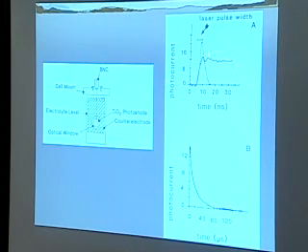I'll point out, when you're looking at the fast time scale here, even though we've done a lot to minimize noise, if we were doing NMR spectroscopy, we would call that ringing going on there. That is, we have a bit of an impedance mismatch between our oscilloscope that we're putting this out to and our wires and our cell here. And so we have some signal bouncing back and forth. And all this ringing here is due to that. So the real signal is on this longer time scale here. So that's the experiment.